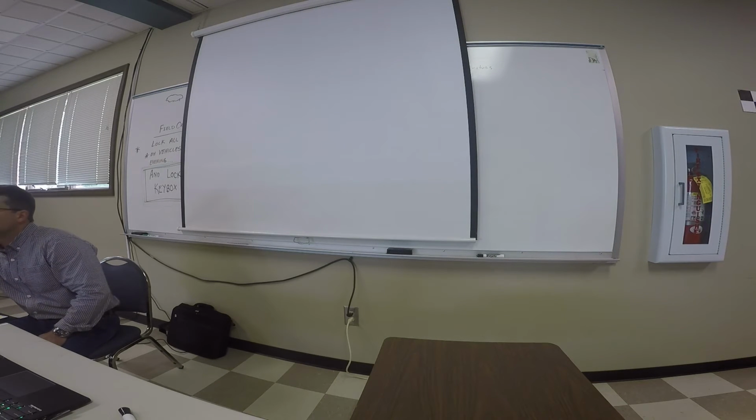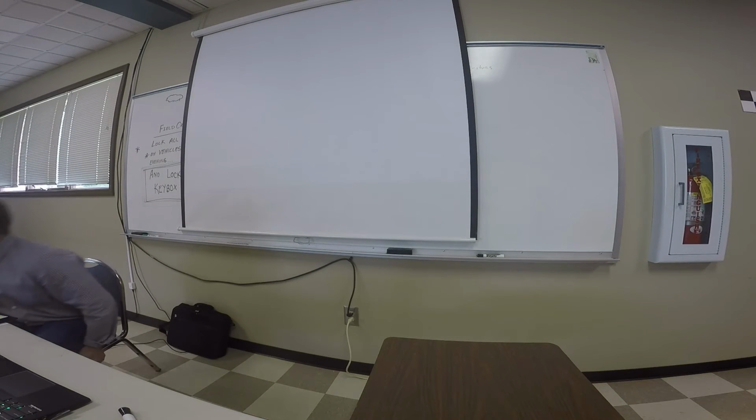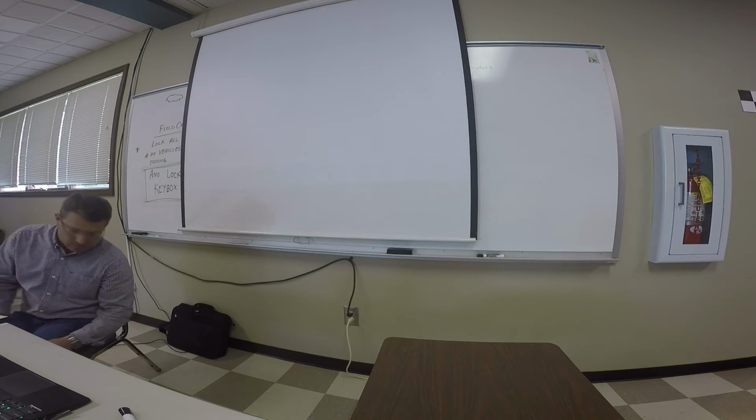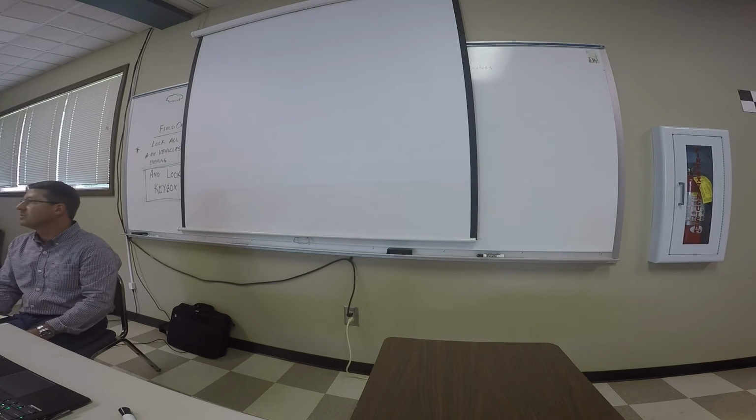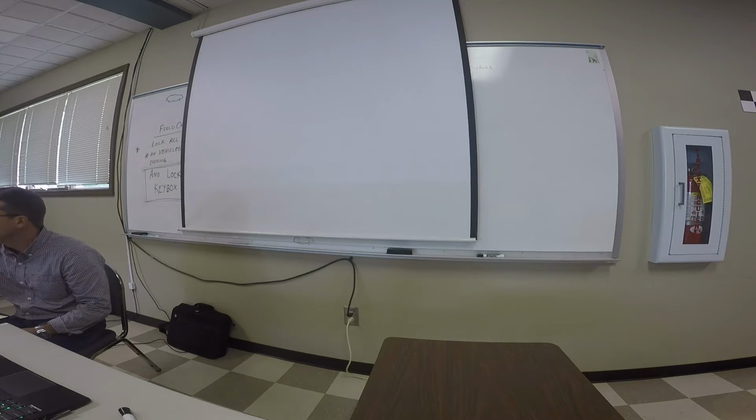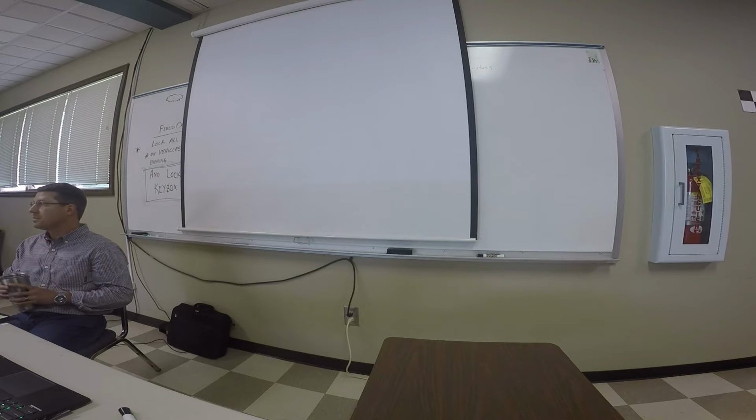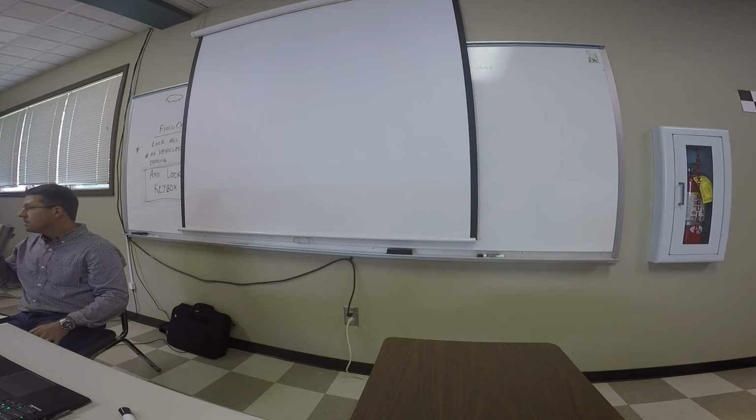Dashes and spaces. Does everybody know how we use our dashes and spaces? All right, Rob, what's a dash do? A dash is if you want to identify what you're talking about, like a descriptor. What would you add a descriptor to? So if you're doing a gutter line, you want to do a dash, because you know how thick the gutter line is. So for the gutter line, you want to dash 24-inch curved gutter, and that lets the project manager know what type of gutter line to put in there.